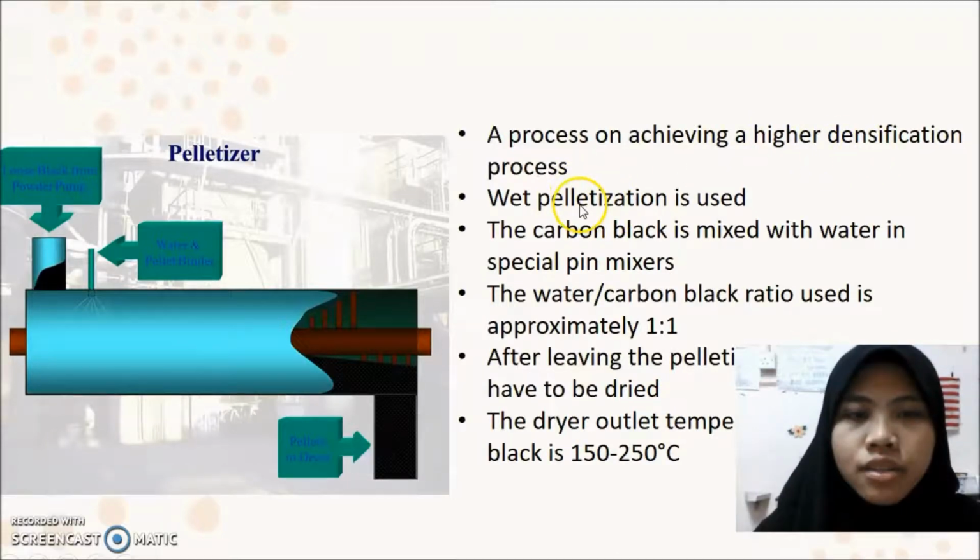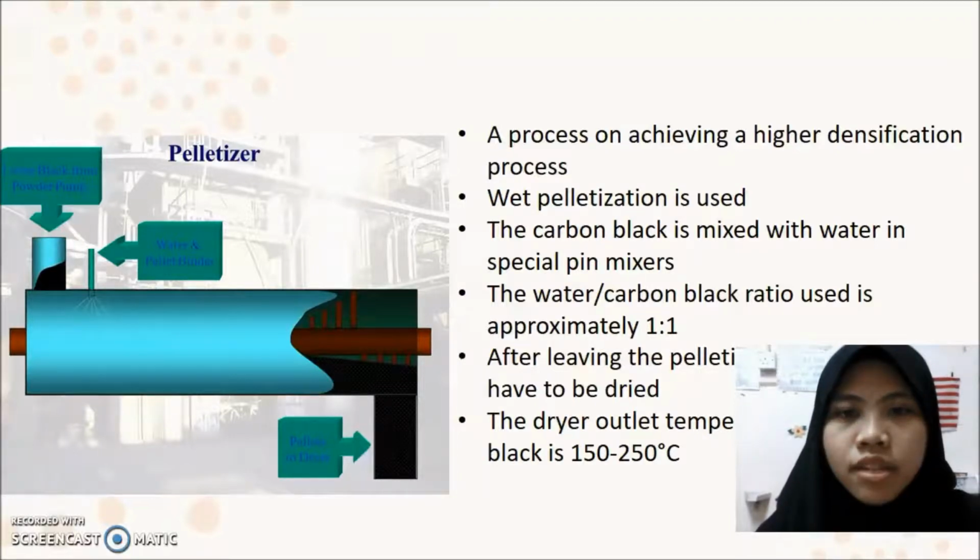By undergoing the pelletization process, the transport volumes of the product are smaller, and it has more favorable free flow properties and reduced dusting. Two methods are used industrially for carbon black granulation, which are wet granulation in a pelletizing machine, followed by drying,